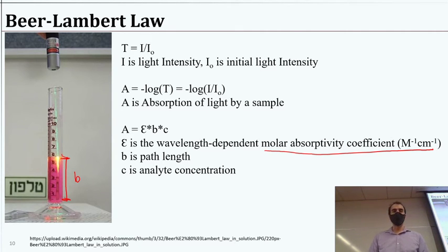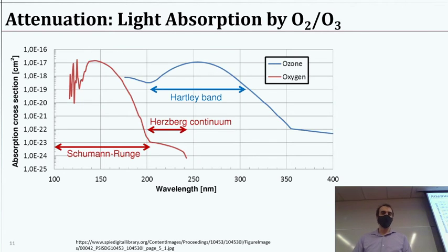So the same stuff applies when we're dealing with UV application to treating water, right? We have water. Stuff in the water is potentially absorbing the UV, maybe the water itself, perhaps even dissolved oxygen in the water. If we're ozonating, ozone will absorb. We know the ozone layer protects us from UV, so if you think about that, we have UV absorbing our radiation. And speaking of that, if I were to shine a UV lamp right here at you, you probably wouldn't be receiving much of it.